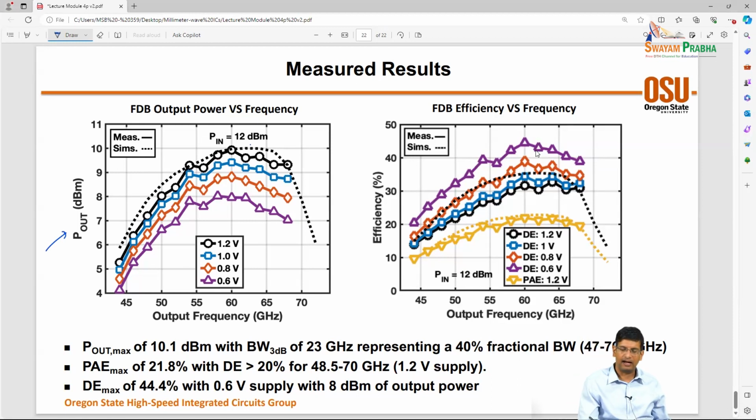And the really nice benefit of building these doublers is that you can get really high fractional bandwidth. So you're not concerned by the bandwidth of the LO path. So a wideband coupler that follows this kind of doubler can create wideband LO quadrature signals that you can use in your transmitters and receivers with a single low frequency LO. So if we have time and we look at some of the array architectures, you will see that a lot of the arrays have some sort of frequency multiplier in them to reduce the input frequency.